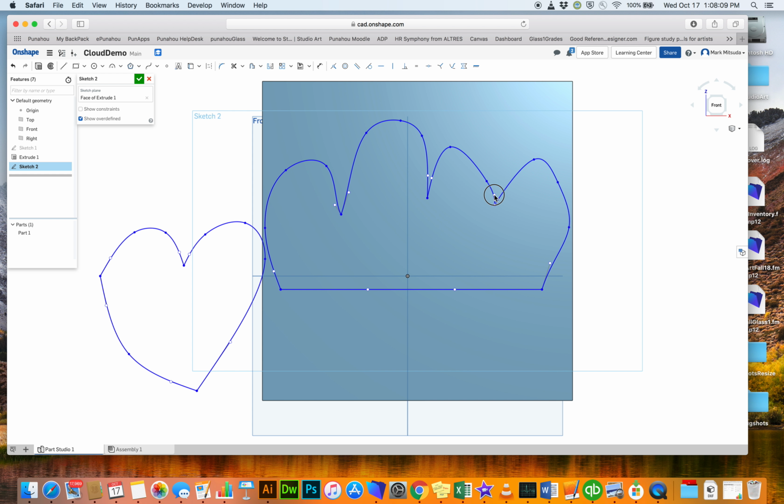I've got the points, and then the end points of the splines have these little handles, and what the handles do is manipulate the curve of the shape. So when I drag these guys around, I can change the curve by moving those points, but I can also change the curve by moving these handles around. Okay, so that's another way I can change my curves.